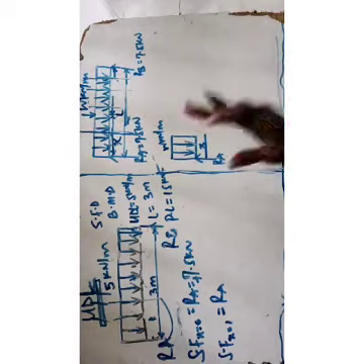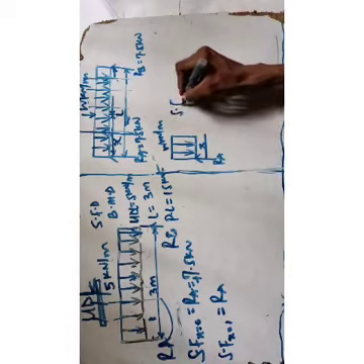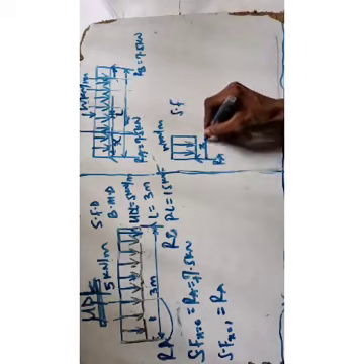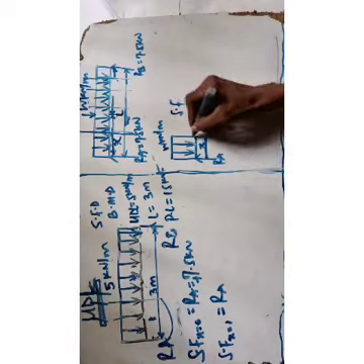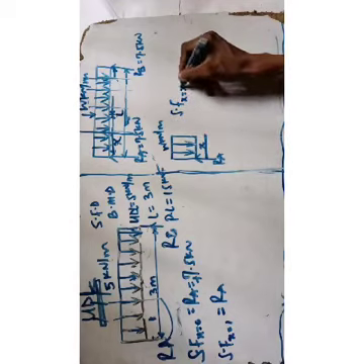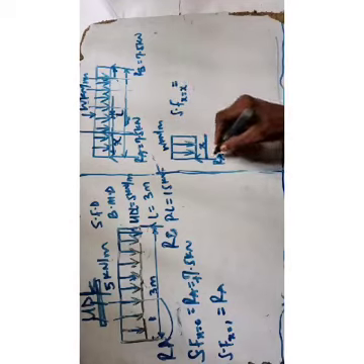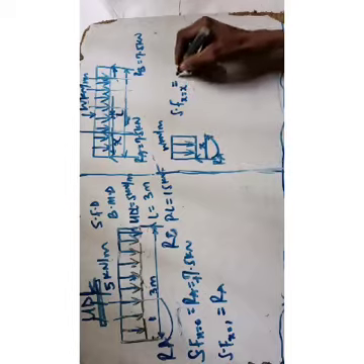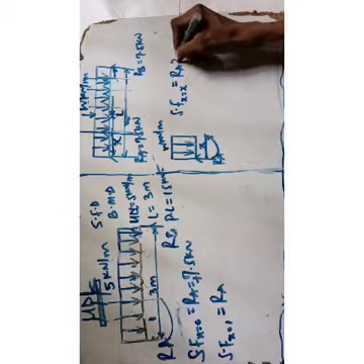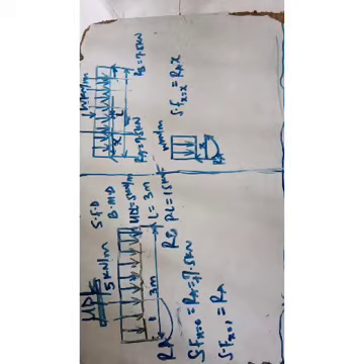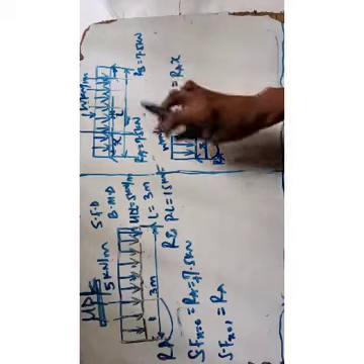Now you want to take the shear force. That will be the shear force at point X. That means at this point X, when X equals X, you take the moment, right? That will be RA times X, unlike the shear force for simply supported.